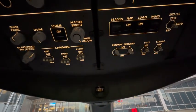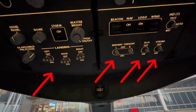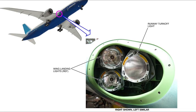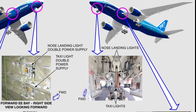First things first, the light panel. Now, a lot of this is self-explanatory, but component location is also important. Landing lights, runway turn-off lights, taxi lights, and strobes. These are the nose landing lights. The left and right wing landing lights are embedded into the root of the wing right there, which is also right next to the runway turn-off lights. Taxi lights are the smaller ones that are right next to the nose landing gear lights.